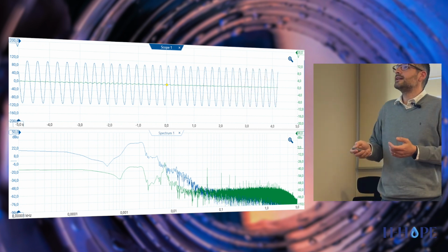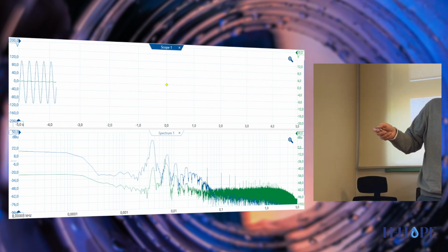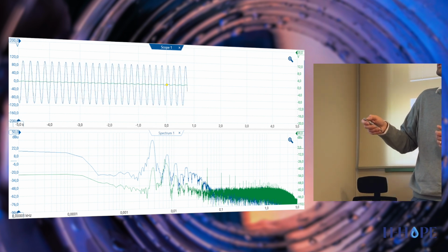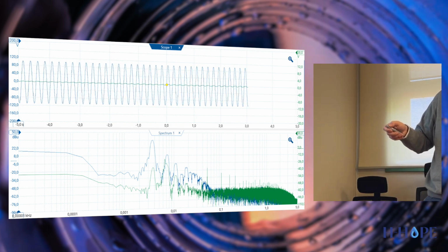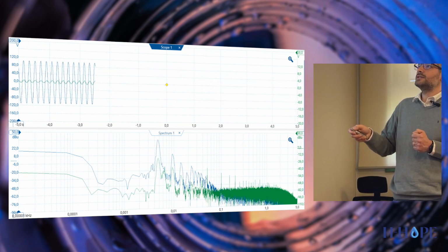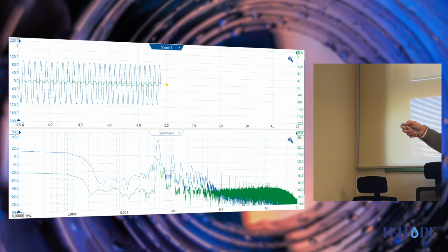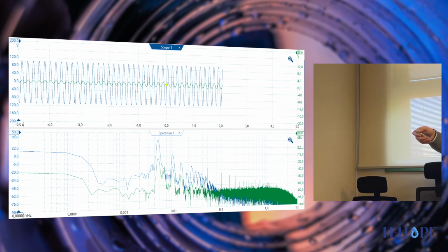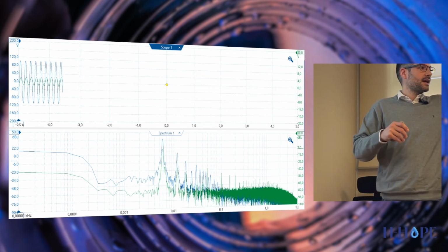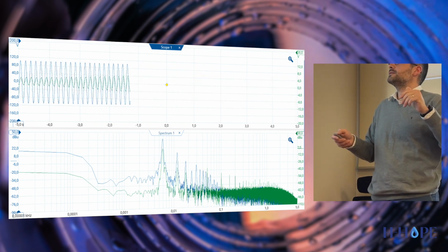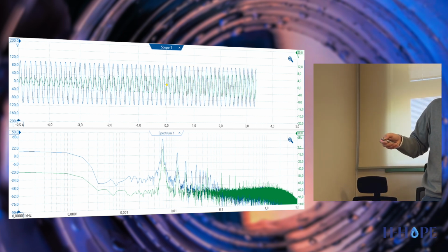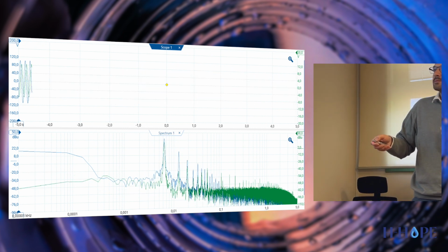beam modes, so we just use the ones excited with the piezoelectric patch that is exactly on the symmetric axis. Now what we can see here with the oscilloscope is the excitation signal, the blue one, and the measured signal. As we increase the frequency, the green signal, which is the output voltage, will increase up to the highest output voltage that can be reached, and then will decrease. The image below is the spectrum.